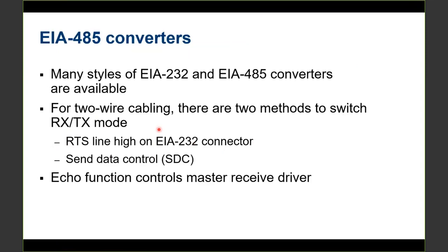If you use the other method, there's this SDC mode. When it sees a proper serial frame on the 232 port, and by proper, there are dip switches to tell it which baud rate this converter is operating at, it sees that proper serial frame coming in on the transmit in pin on this device, it's going to turn on the transmitter and send that data out.